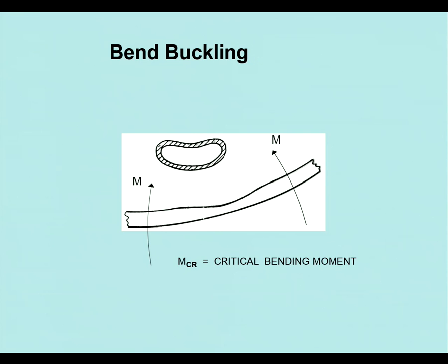And if anybody's doing some big pipelines like water mains and things like that, where they put a concrete jacket around it, then the concrete jacket, but what's this point here called? If I do that, it's going to bend about that. So what's the stress going to be at that point? Zero.